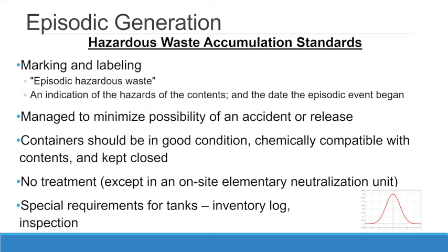Again, the tank must be leak-proof and in good overall condition, and must be lined with materials that do not cause a reaction with the waste being stored in it. You need to take precautions to prevent overflow, and you need to inspect the tank at least each operating day.